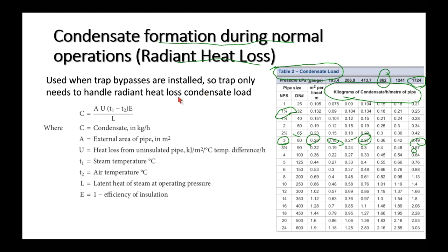Why is it in such weird pressure? Why weird pressures? Because what Pan Global probably did here was they took pressures in PSI and did a direct conversion instead of doing a soft conversion. If it was up to me, I would call this one 100, and I would call this one 200, and I'd call this one 410 or whatever, right? And this one here would be 1725. That's why they're weird pressures, because somebody with a calculator converted the numbers directly from US standard units.